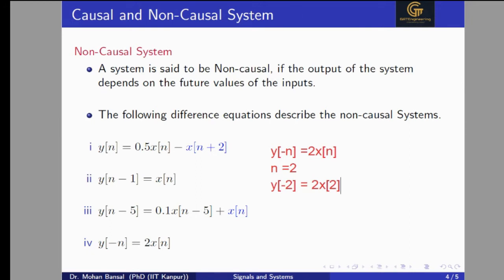And one important thing is that for the causality or non-causality, we don't bother about the amplitude value. We just need to check the relation at the time index in the input signal and the output signal.